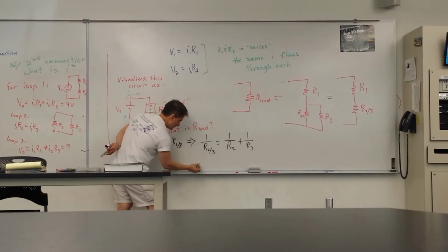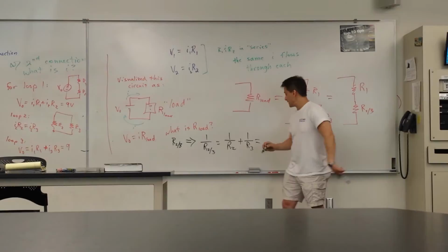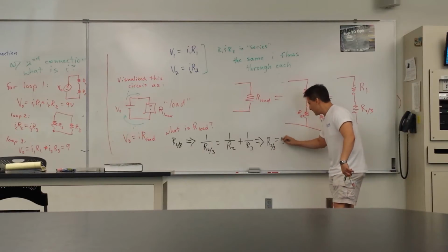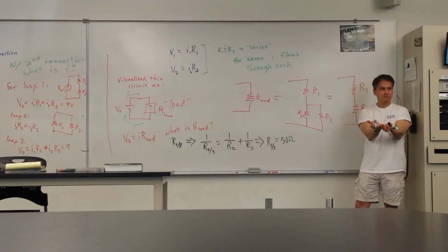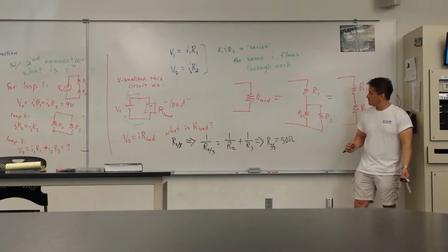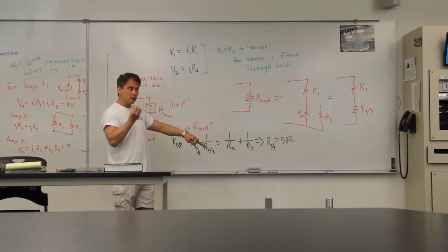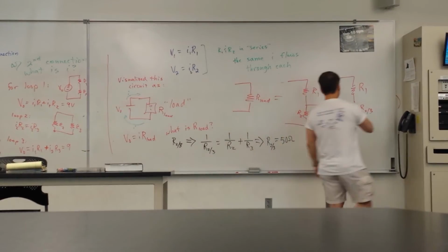Which in this case allows us to say, since they have the same value, I'm just going to cut to the chase and say that this implies that the combination of R2, 3 will be 50 ohms. Two equal pathways mean you double the capacity, all things being equal. So, making that one little logic step allows me to say, oh,